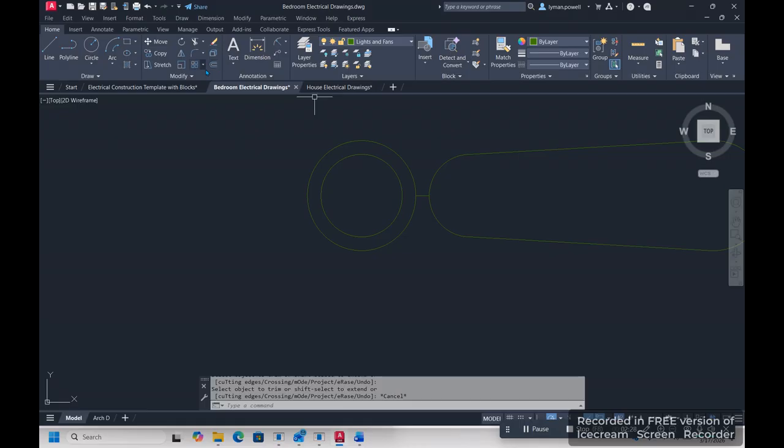And again, we are working with the offsets. So on the offset, I'm going to click, I'm going to do this 0.5, and we're going to offset this 0.5 in this direction, and then we're going to do it 0.5 in this direction. So our bracket will be about an inch long, and then we're just going to delete the one in the middle there. So this is one of our blades of our fan. So now we just need to make this 5 more times. This is a 5-bladed fan.